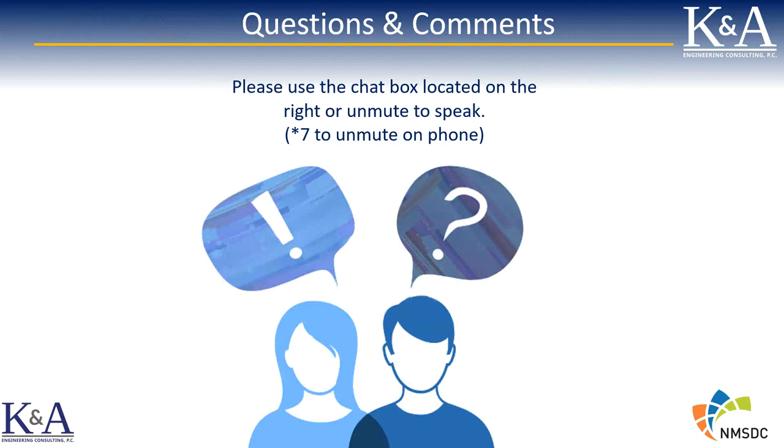My approach is typically to, even though it costs more upfront, I think the benefits for the life cycle operation of the substation in terms of maintenance, in terms of reliability and safety and so on, generally justify using redundancy everywhere you can. So yes, there are redundant servers in most of my designs, unless the customer strongly objects. I recommend using redundant components everywhere.